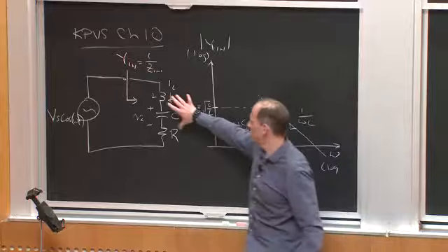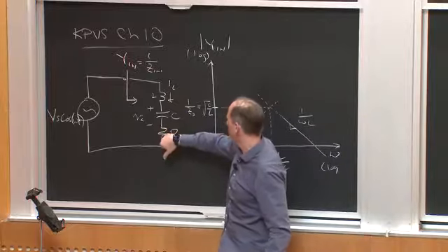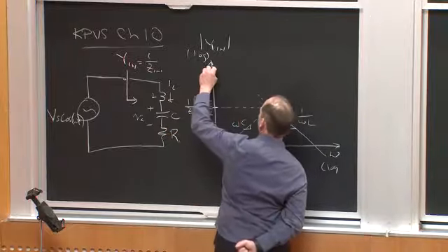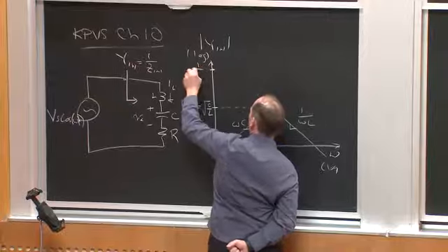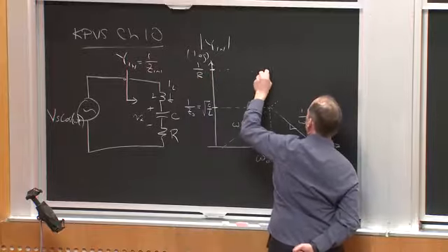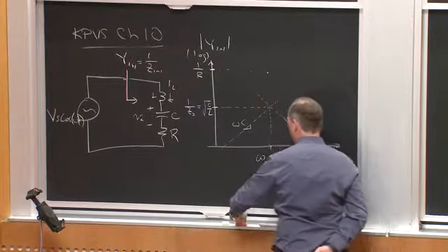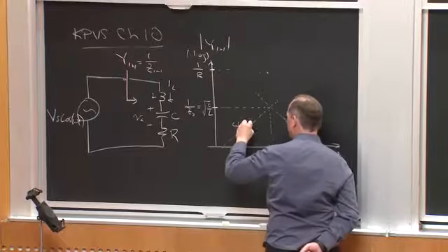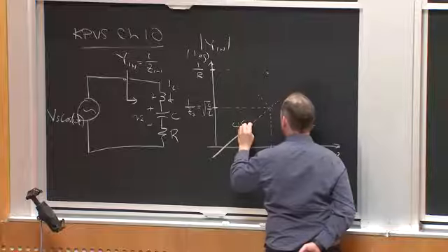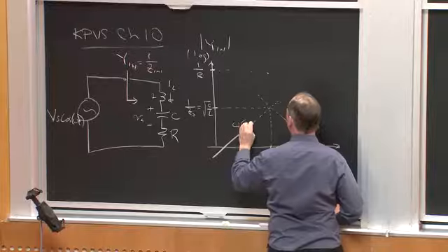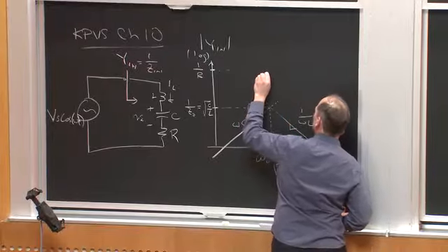And right where these impedances cancel, the admittance goes to being 1 over R. So maybe it looks something like this. I have 1 over R where it peaks up to. So maybe my admittance characteristic looks something like this. It rises. I'll have some region about which it peaks up.